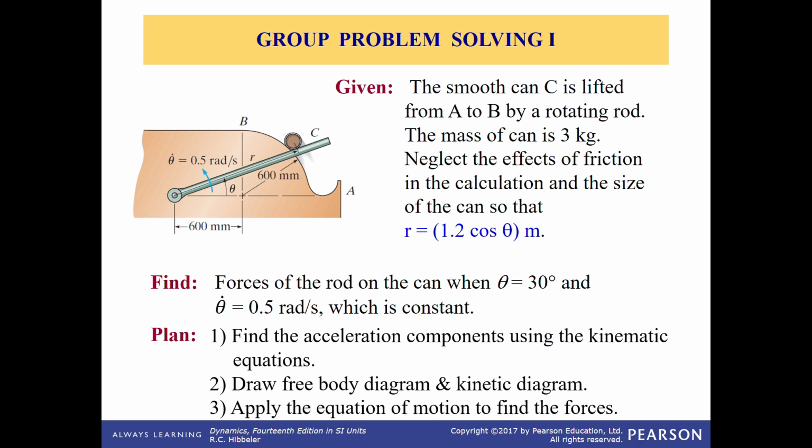Okay, the same technique or the same steps we need to apply. First, actually, you need to draw the free body diagram and kinetic diagram, and later find the acceleration components using the kinematic equation.